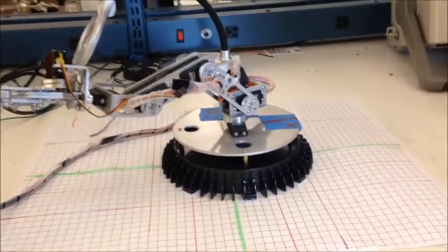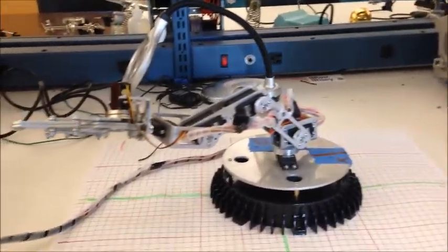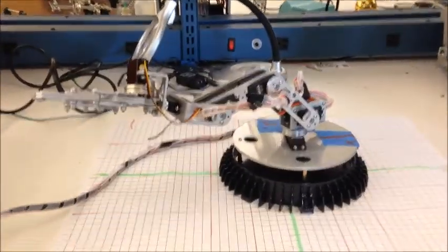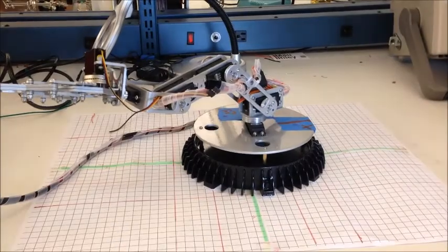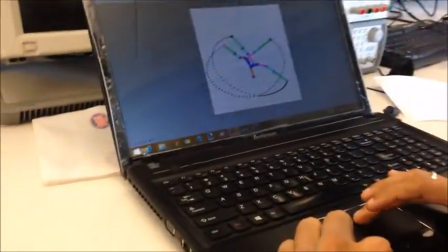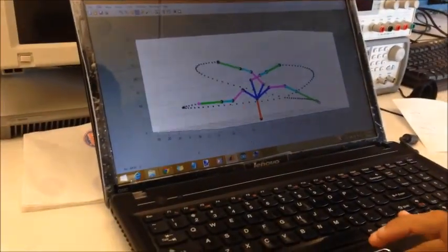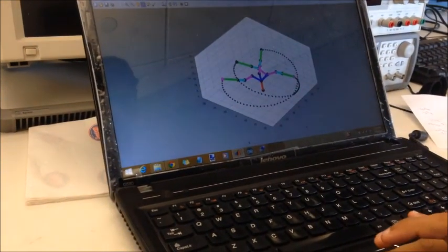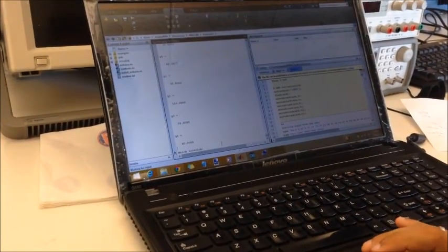So we're not moving as fast as we could. We've slowed the robot in the simulation down quite a bit because the high torque of the motors causes the robot to get unstable. So we're just moving them slowly with the motors. Here you can see in the simulation window all the 4 locations and the trajectories, how the robot reached there. And the program runs in a loop, so if you want to go to another location from here on, it just asks for a location number, so you just enter the location number and the robot goes there.